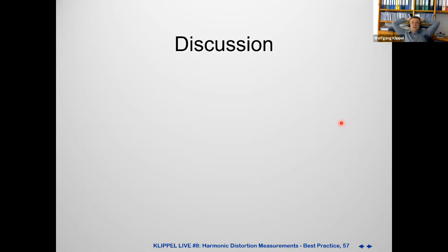But the main problem are the modal vibrations, the rocking modes, which have usually a Q factor of 20, 30, 40, or some other modal vibrations from the surround mode and so on, which have usually a Q factor of 10 and higher. And they are critical. If you are working with headphones, for instance, then sometimes you have very narrow, very bad resonances, and they may generate some rub and buzz. And to get the rub and buzz, you have to consider those resonances with the sweep speed. Interesting.